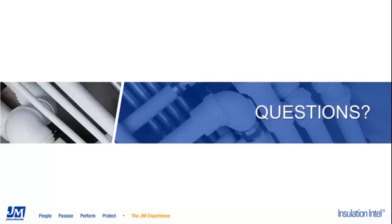The first question is for you, Meredith: in the R12 portfolio for Microlite, is the R12 out of package or installed? Do you advocate full thickness completely around a duct to maintain R value? Yeah, so the R12 is the installed value. The out of package R value for our 4.4 inch thick duct wrap is R15, and we're taking into account that 25% compression so that your installed R value is going to be an R12.